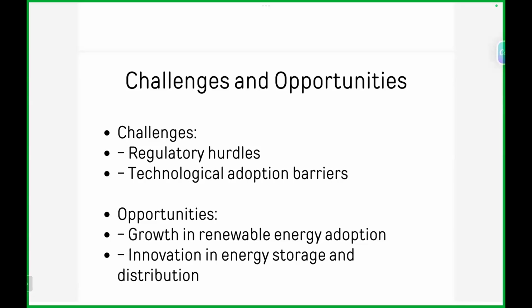Especially, the government has slots for high tension consumers, where the C1 slot is morning 6 to 10, the C2 slot covers evening 6 to 10, the C4 slot covers morning 10 to 6, and the C5 slot covers night 10 to 6. Out of these 4 slots, renewable energy can supply on the C4 slot, where today, by having energy storage, the government is planning to have round the clock distribution by adopting energy storage systems.